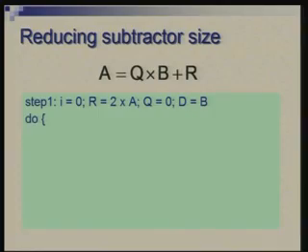So, in terms of algorithm, what we do is as follows. Now, you would notice that D will start with the value B. Okay. It is not B into 2 raised to n minus 1. D will have value B. D will be an n bit register, whereas R has the dividend placed in the correct position, so that the dividend and divisor are relatively positioned correctly.